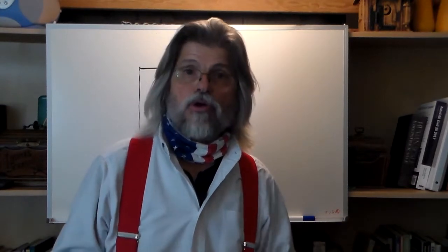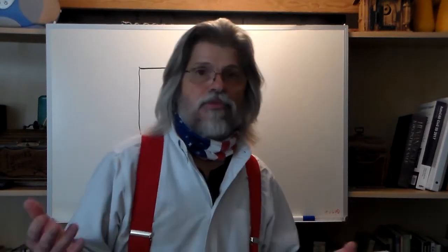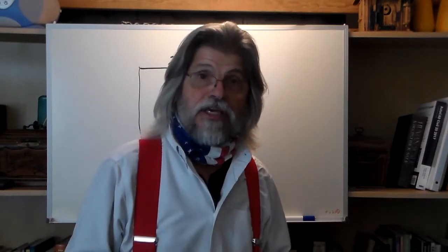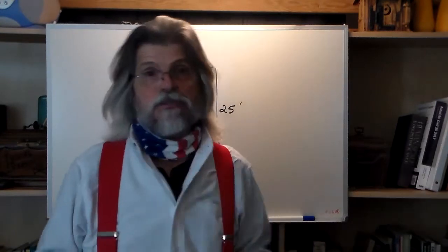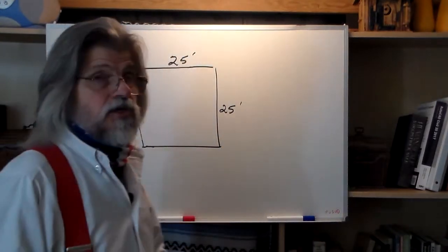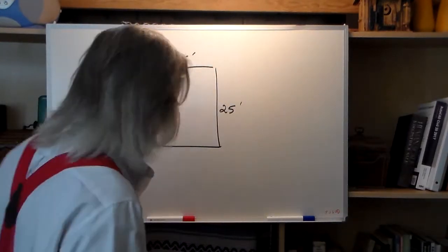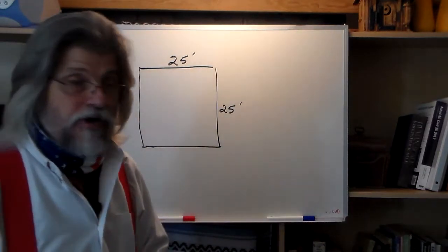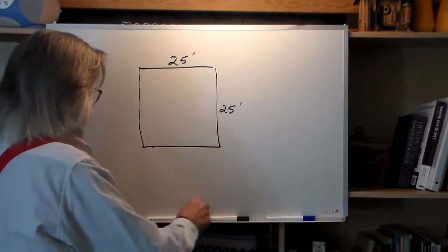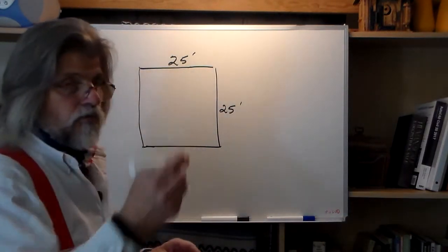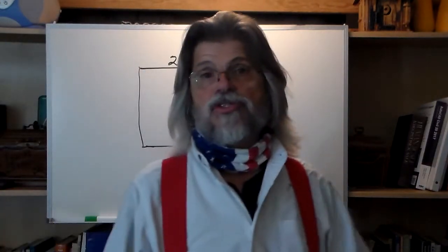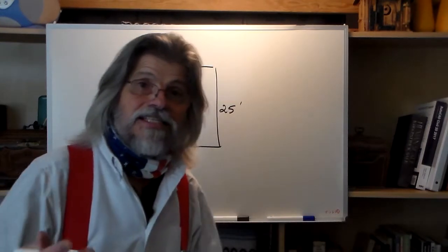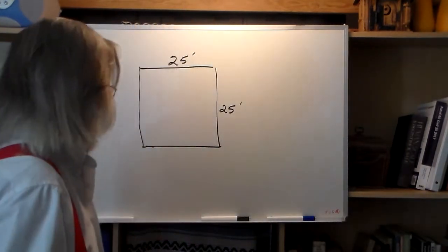The next thing we need to do is know how deep an amount of dirt, or what depth of soil we're going to be moving as part of this construction process or as part of the design process. So now, to work our example, I'm going to give you some elevations. We're going to start off with the red pen, and I am going to give you the elevations of the land as it sits now. In other words, the natural ground.